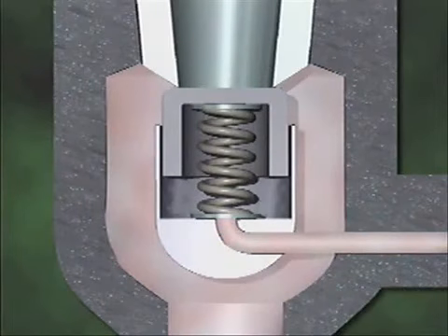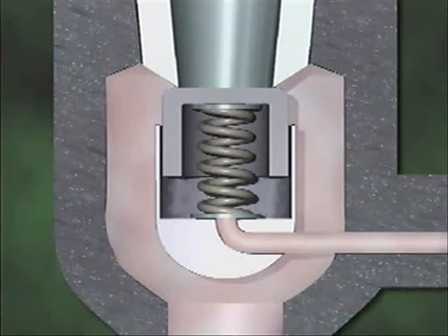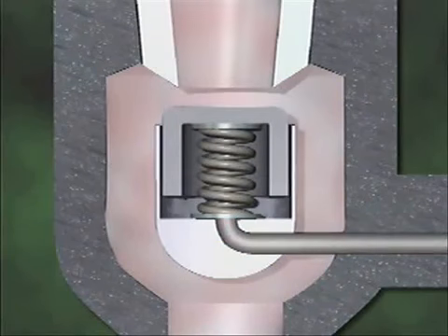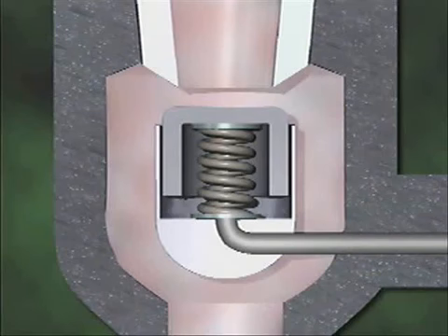The excess pressure that's relieved by the pilot valve comes from below the disc in the main valve. The amount of pressure that the pilot valve is capable of relieving is greater than the amount that could leak between the disc and the disc guide. When this pressure is relieved, the only pressure that remains on the disc is the pressure that's above it.